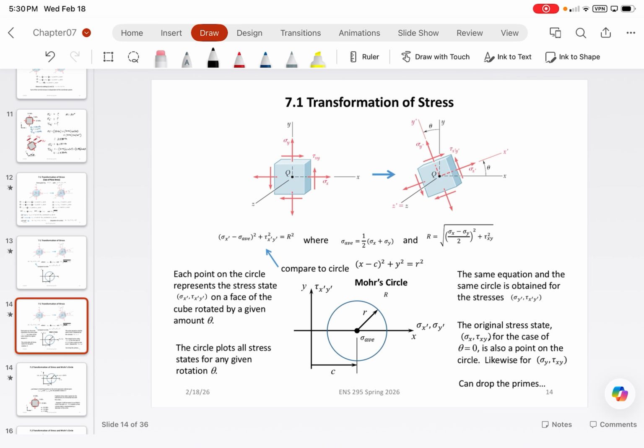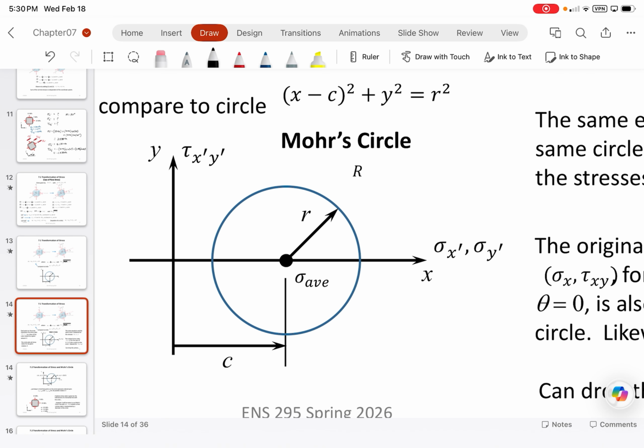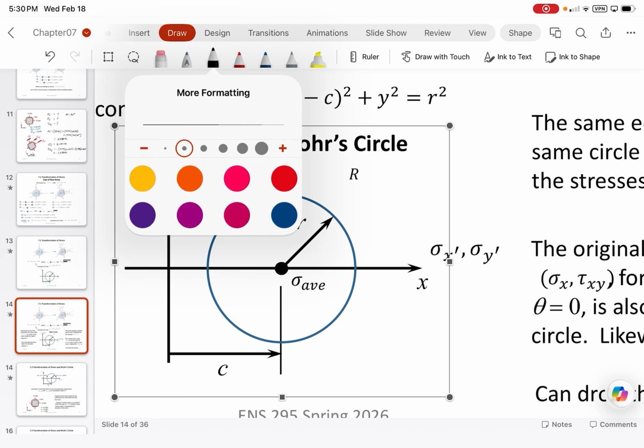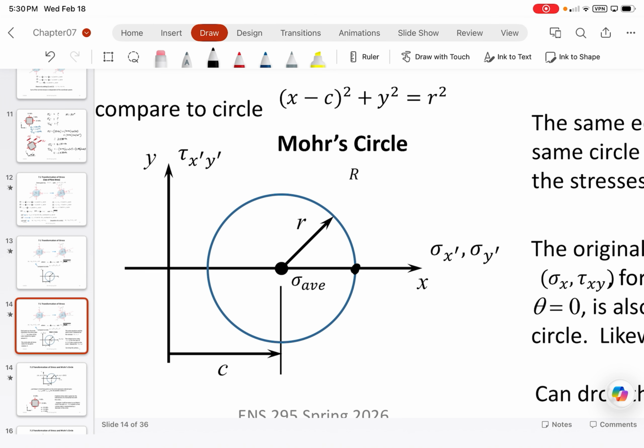All right. So when we're drawing this, we call this Mohr's circle. A guy named Mohr developed this. We basically treat it where the x-axis is all of the normal stresses that are occurring. So it's a normal stress coordinate along the x-plane, and then we treat shear stresses along the y-plane. And so what you guys will note is that the maximum normal stresses we can have are really going to be here and here. These are the maximum and minimum normal stresses that the system can undergo.